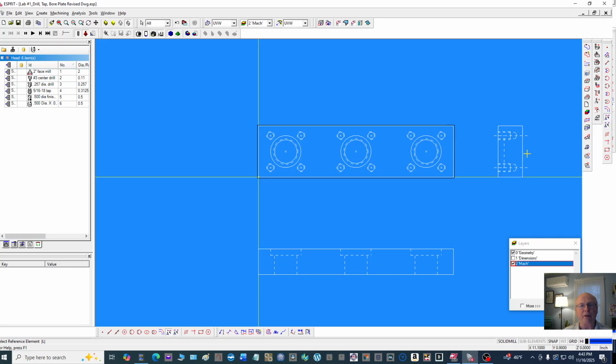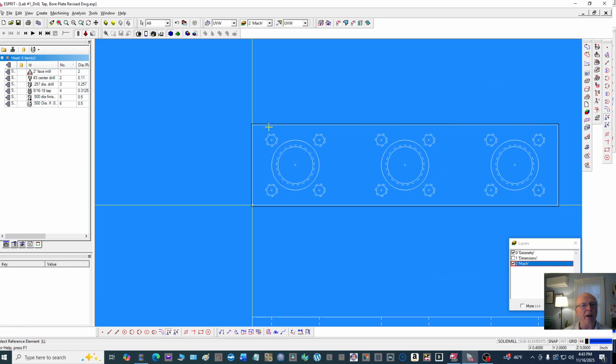We'll deal with the thickness here a little bit later. Right now, we want to make sure that we have a chain that represents this extra material all the way around here, for the purpose of making sure that there's stock highlighted there so you can see the machining process itself. Now we'll also have to create a chain for the real part itself too.